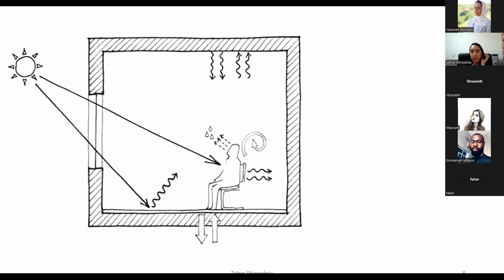The human body exchanges heat with the environment through convection, which depends on skin temperature, air temperature, and air speed; radiant heat exchange, which depends on the temperature of the skin and the temperature of the surface enclosing the space; and transpiration, which can turn into sweating, and respiration, which results in the evaporation of water with the consequent removal of heat from the skin or lungs.